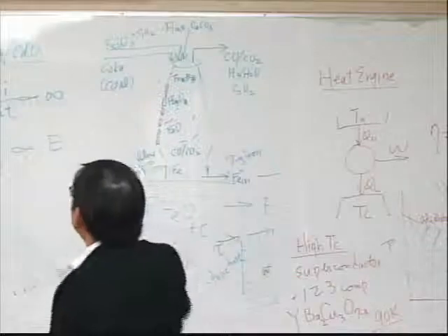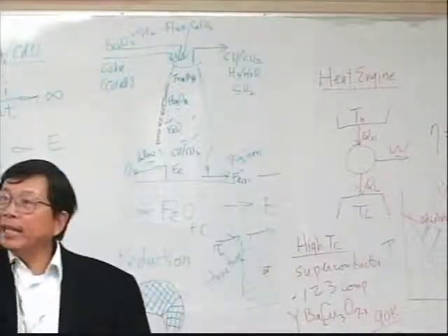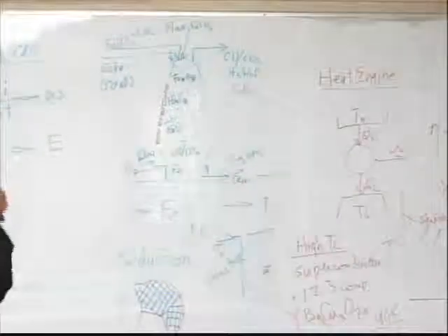It's all because of this huge di/dt. That di/dt creates such a high voltage, it breaks up the air, and the temperature can be very high. We did some measurements: plasma temperature can be a few thousand degrees C, for a very short time. Very often you see the electric contact surface will melt. If we use pure copper, it will melt together.